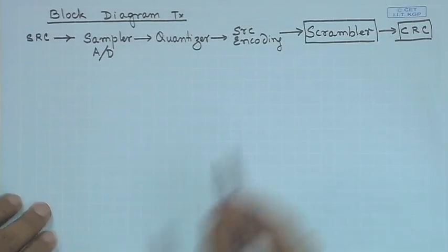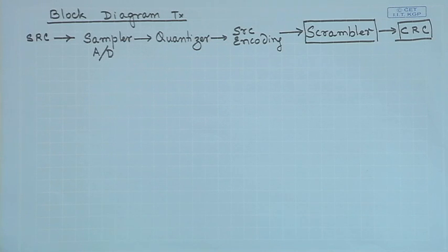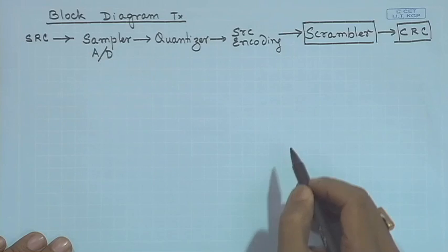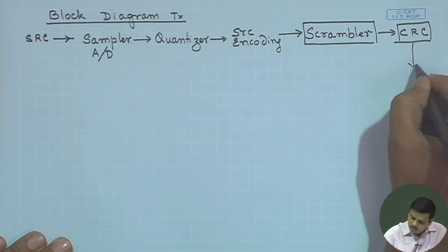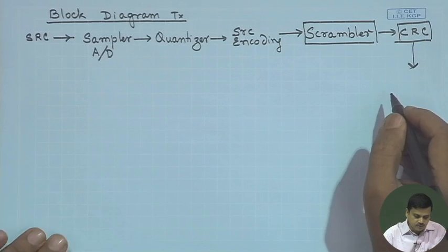The job of the CRC, it is known as the cyclic redundancy check. Cyclic redundancy check is like a code. Suppose I have a message, it is like parity you can think of, let us say odd parity or even parity. I was explaining in one of the early lectures, suppose I have 3 bits and I want to make it odd parity. I would put one extra bit where the sum of ones in them will count to an odd number. If the receiver finds that it has received an even number of ones in any group of 4 bits, it is going to send back that I have received an erroneous group of bits. CRC is basically used for that. So, it is useful for error detection.